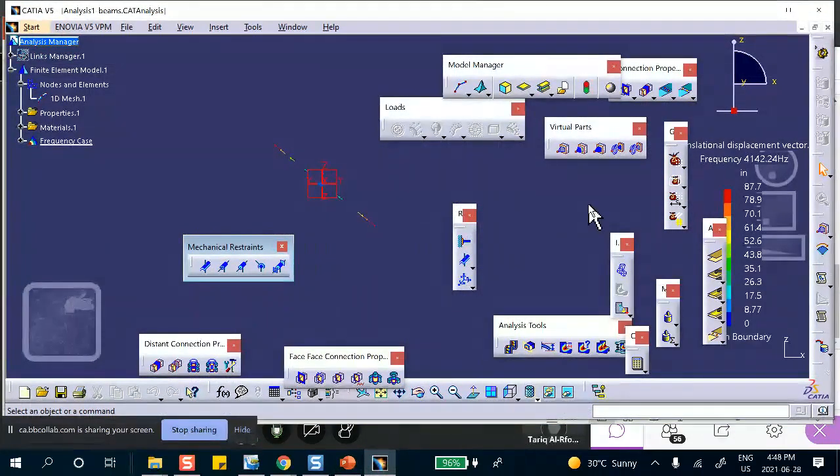We didn't need to join in this. No, okay. Because I drew it as a wireframe. I drew it as a line in space. Okay, but if you drew it as a sketch, you must join. You cannot measure. Okay, and for homework 6, we had the buckling question. Yes. I did not mesh, and it was sorry, I did not join, and it all went through good. So this makes me a bit more confused about when to join and when not to join.